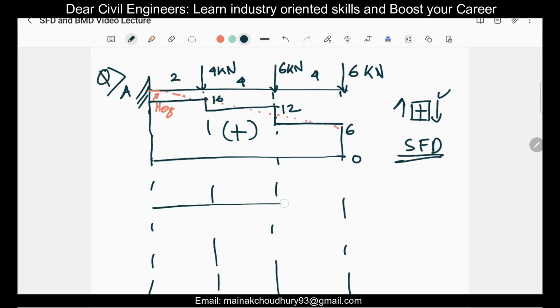And then let's do the bending moment diagram. Since hogging is negative, we'll take it along the negative direction. Here is the free end, and at the free end the bending moment is 0, so it will start from here. Let's name the points A, B, C and D. At this particular point, the bending moment will be 6 into 4, which is 24, and it is negative since it is hogging.